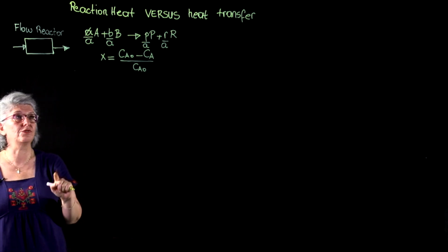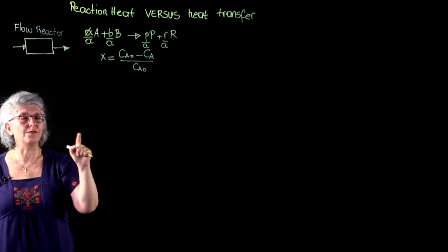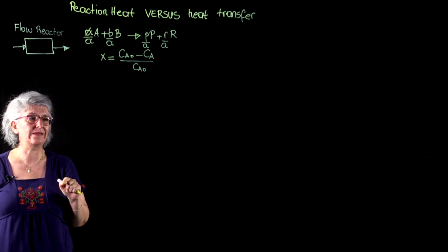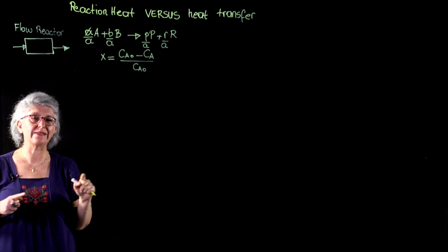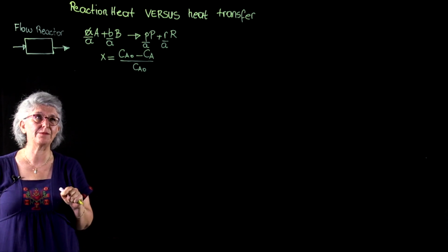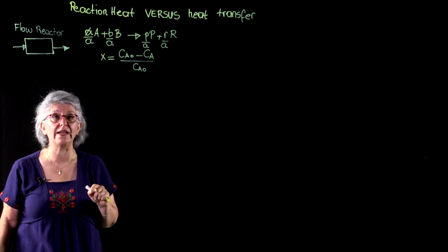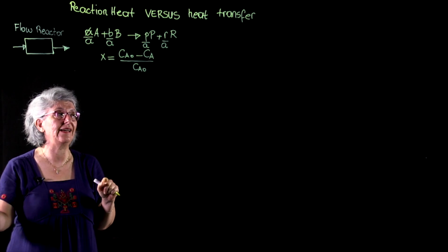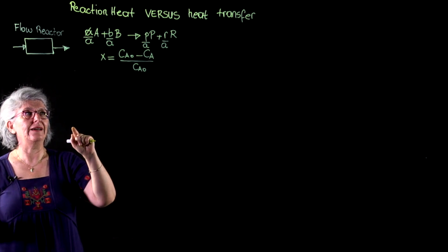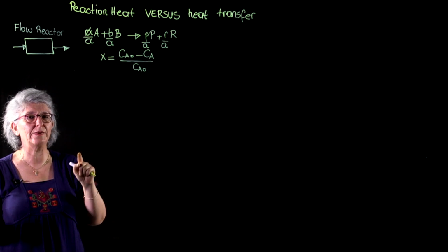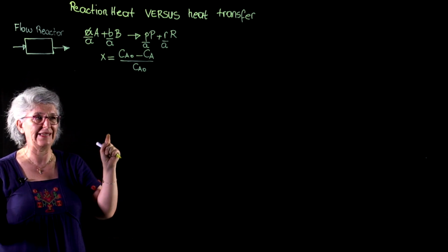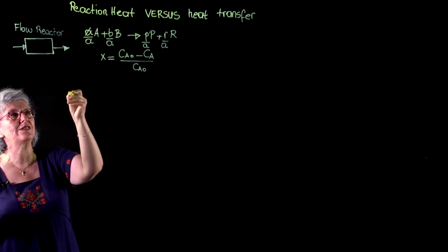Here we are going to evolve the energy balance in its most general form to an energy balance that incorporates a chemical reaction. And before we do that, we have to have a rigorous material balance analysis in our hands. In order to be able to get this rigorous analysis, we have to have a stoichiometric table.